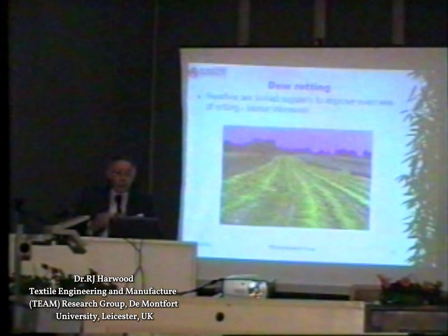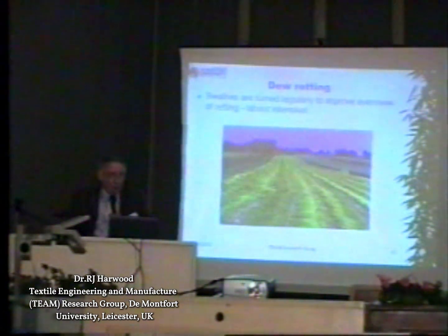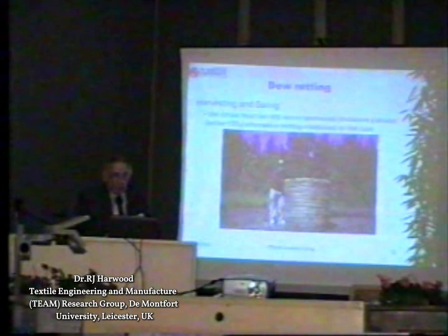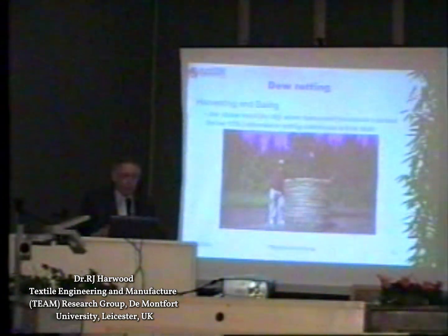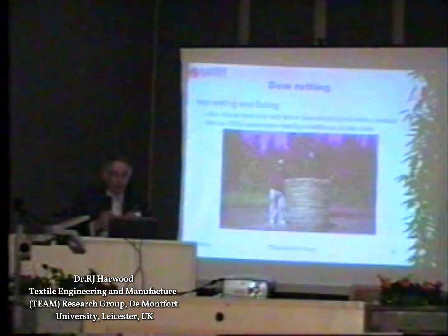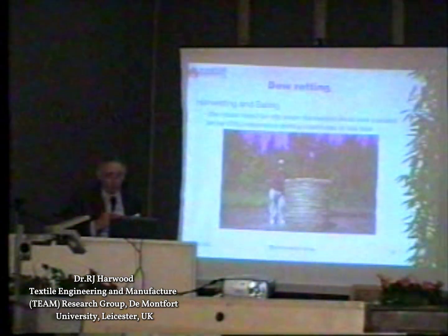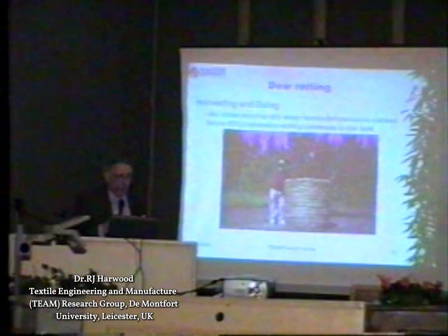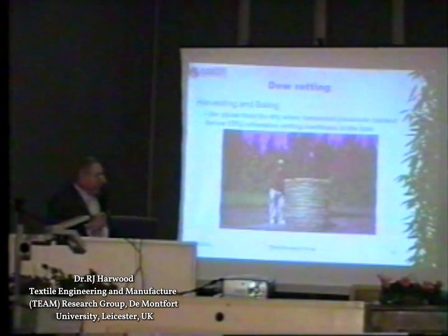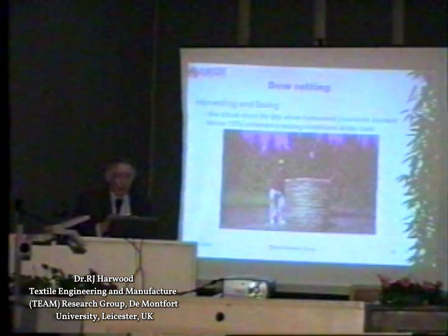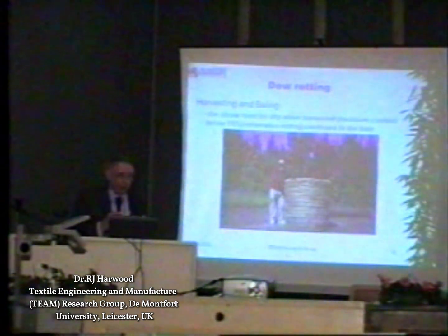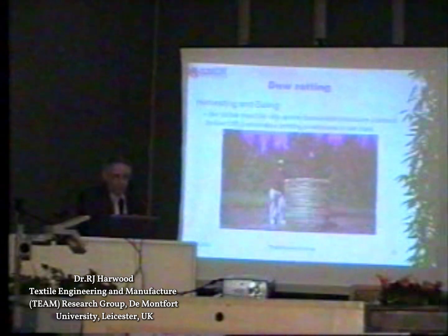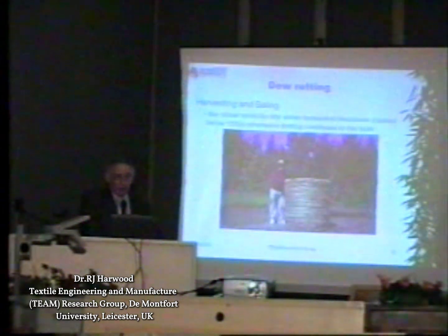And these swathes are turned from time to time, and as the plant dies, it gets attacked by microorganisms, and it rets. And finally, it's baled. I'm sure most of you know about these processes, but the important thing is that the bale, if it's being collected in normal processing, has to contain somewhat less than 20% moisture. 15% is not a nice amount of moisture. Otherwise, retting will continue, regardless of the fact that the crop is being harvested.